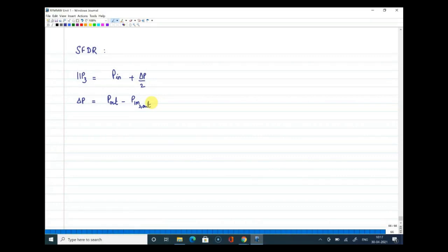Now, all right. So now what I will do is, in that case, I can write output power in dBm. Output power in dBm can be related to the gain directly as the input power in dBm plus the gain of the circuit in dB. So input power plus gain in decibels will give you definitely the output power level.